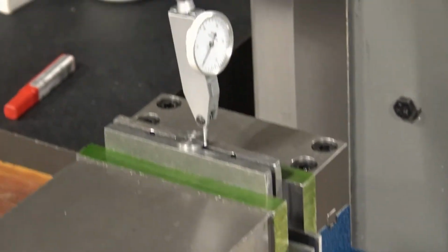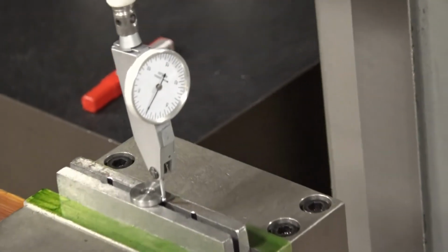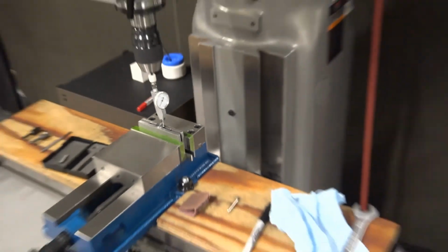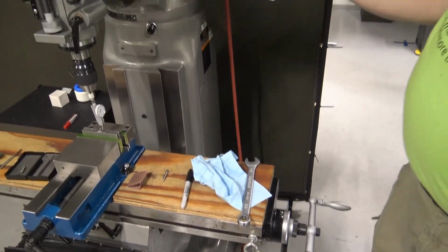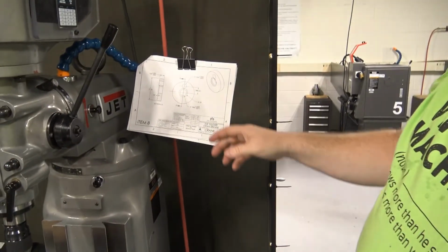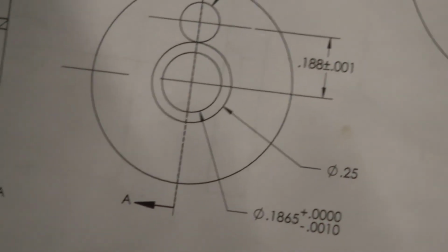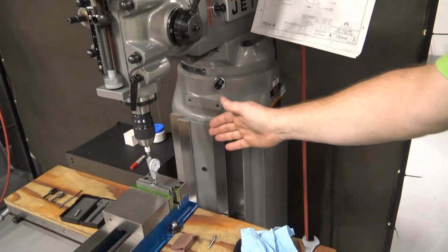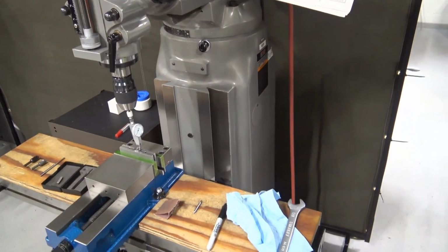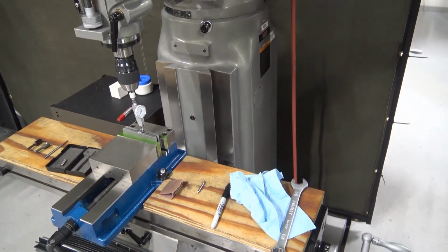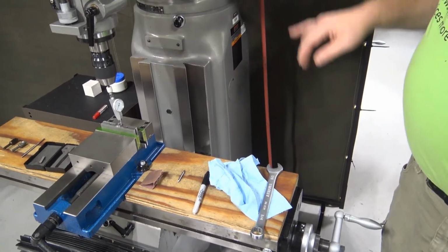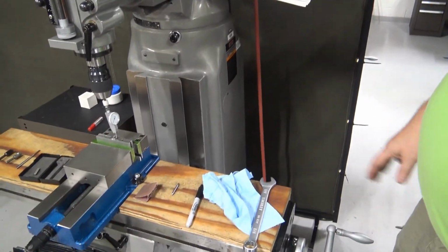So now this is the position where I have to take backlash out of the machine. And when I move off the distance, which I'd like to be off 188 thousandths plus or minus 1, I'm about as good as I'm going to get front to back. So I don't even worry about the front hand wheel taking backlash out, none of that mess. But 188 thousandths.